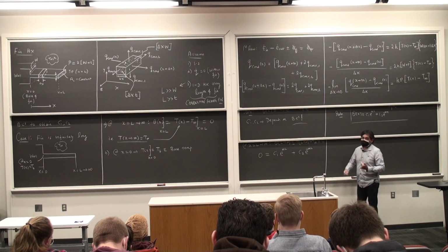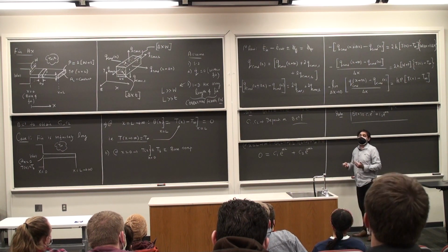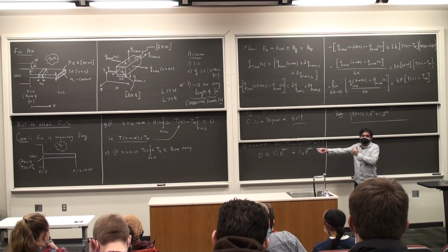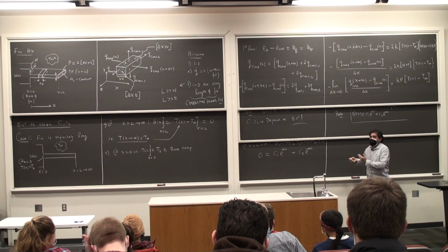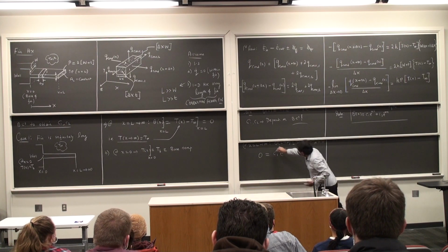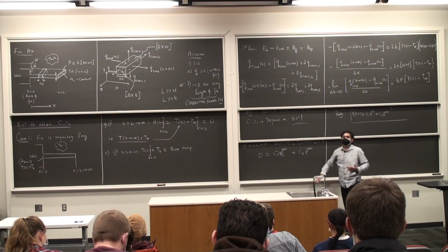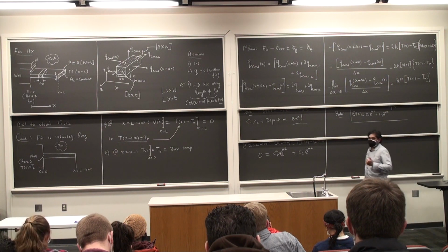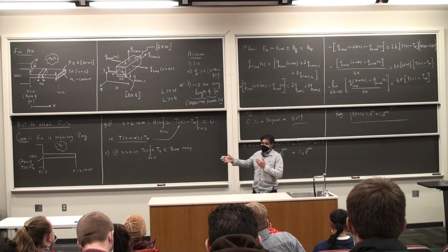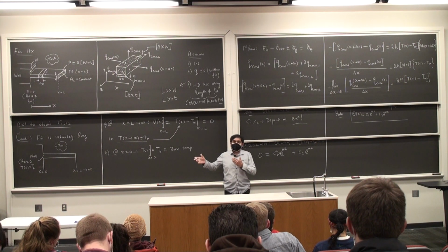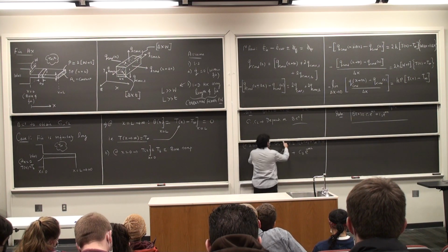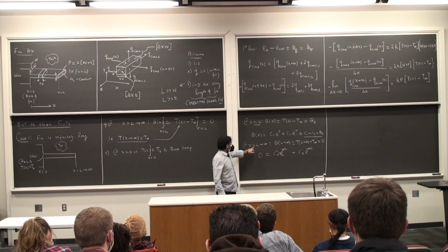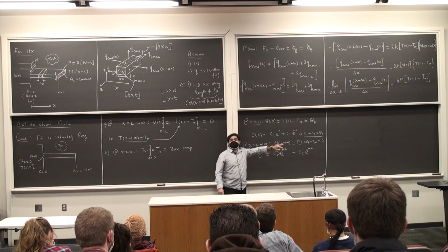which automatically should suggest that if this equality has to be maintained physically, which is obviously true, as the length of the fin is very long, the temperature at the tip is T infinity. So if the equality has to be maintained, this term C1 has to be 0. Once again, the fin is infinitely long. The temperature at the tip of the fin is T infinity. If I make that substitution, I see that at L tending to infinity, theta is 0.